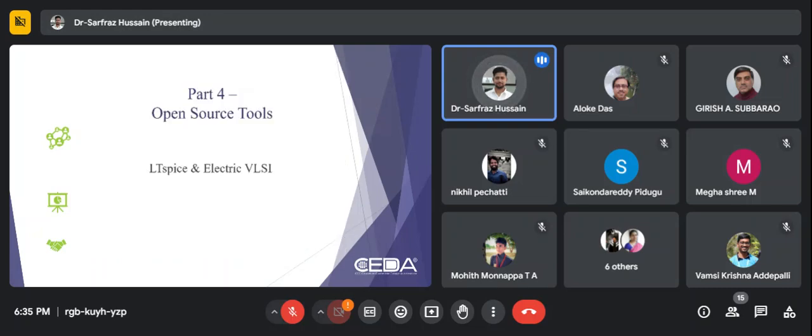After completing this, the final thing I would like to discuss is open source tools. Which open source tools to use? In my opinion, the best open source tools as of now for analog circuit design are LTspice and Electric VLSI. LTspice is mostly used for simulation, whereas Electric VLSI will be used for your layout, your DRC, your LVS, and even the generation of GDS2. So basically, we can do the whole thing using the Electric VLSI tool.